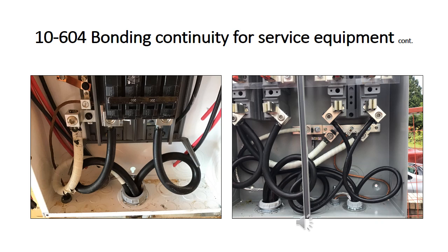On TEC, the bonding conductor is isolated from the cable armor due to the internal plastic jacket. And on ACWU, the bonding conductor is isolated from the cable armor due to the internal paper jacket, and also how the bonding conductor is wrapped tightly between the conductors of the cable.